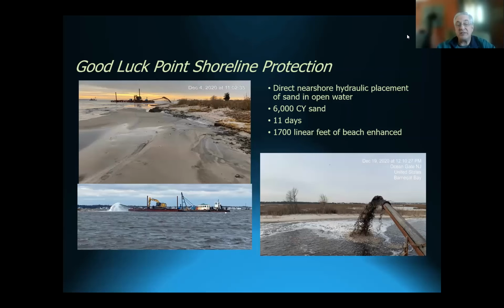Let's talk about the shoreline stuff first. We pumped 6,000 cubic yards of sand from 3 of those 4 channels over 11 days and placed it in the near shore right up next to it. We used what's called a spill barge. So that bunch of equipment that you see there is essentially just a movable platform for the pipe, which allowed us to spray right up next to the beach. And you can see in the foreground of that top left picture how the material, once it settles out, integrates nicely into the existing beach. We placed that material along 1,700 linear feet of marsh.